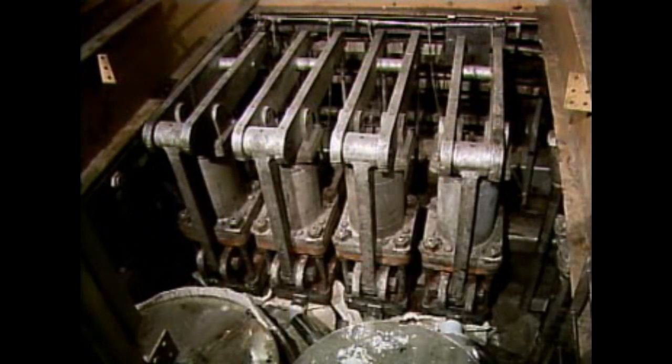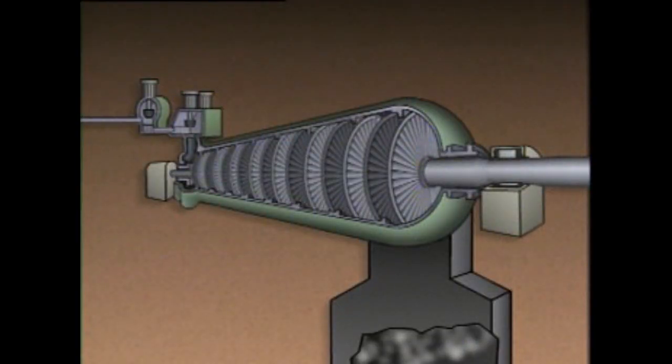Damage from mismatched steam and water flows can be prevented by controlling the flow of steam entering the turbine and the flow of feed water to the boiler. The turbine steam control valves are located in the main steam line to the turbine. They are used to regulate the flow of steam into the turbine. In this illustration of a typical turbine, the steam control valves are located here.